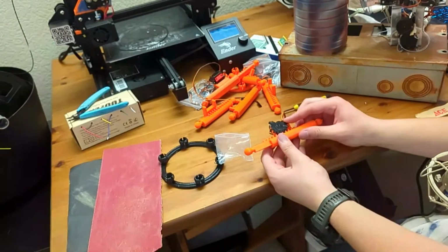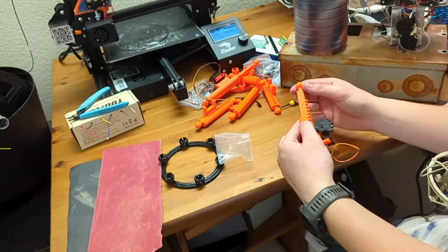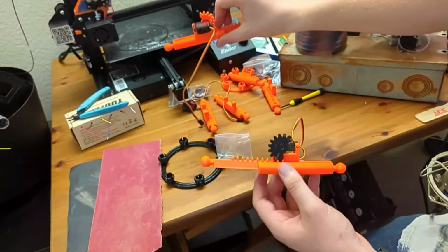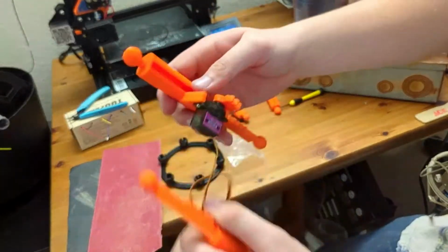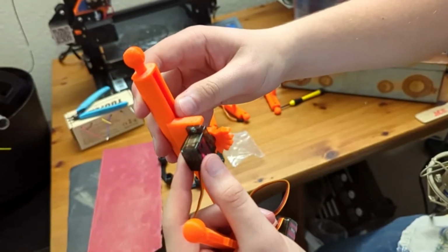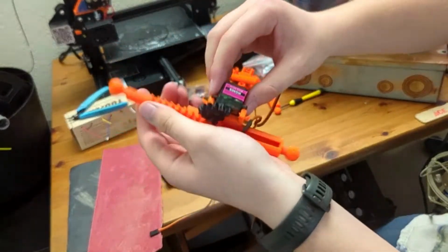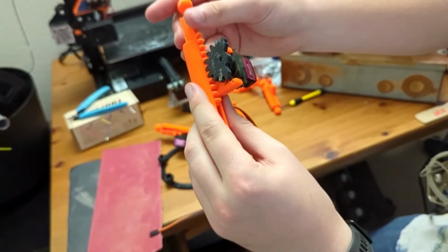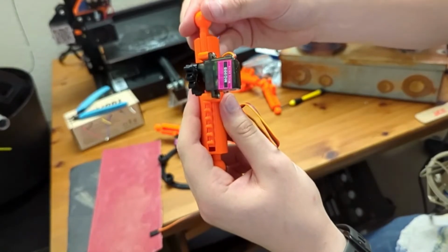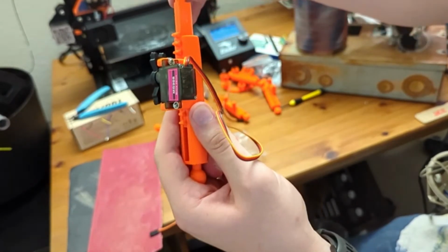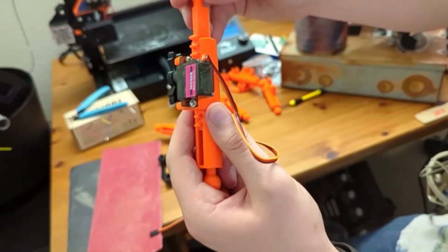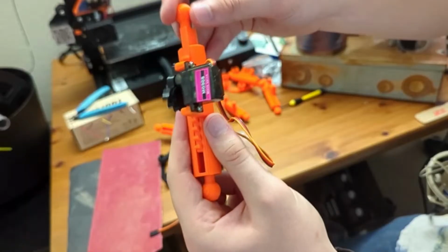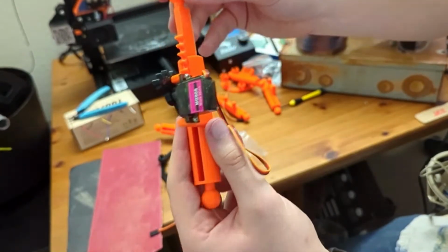So when it's all screwed down like this is actually a lot better than that first one here. This one I haven't tightened all the way, so there's still a little bit of slop in the servo here. This one I just tightened down all the way, and this pinion gear is actually holding the rack down. It's providing a little more friction, so it's a little bit harder to move, but it's a lot more rigid. There's a lot less slop once it's all tightened down, which is always a good sign. Just like that, so that's working great.